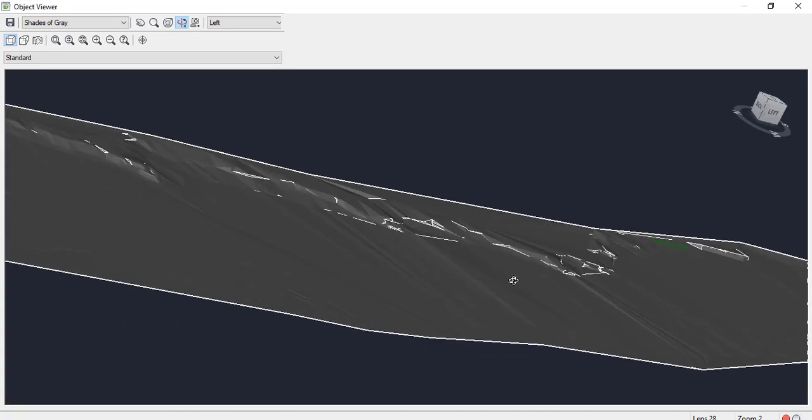You need to confirm that none of your walls goes down from the surface, because we are working with our Seawall design. If we are working with building grading and drainage plans, then we can put the building pad down from our existing surface as per our design to get a basement or anything like this. So we can go down from our existing surface also, but in this Seawall scenario, we will not go down from our existing surface.